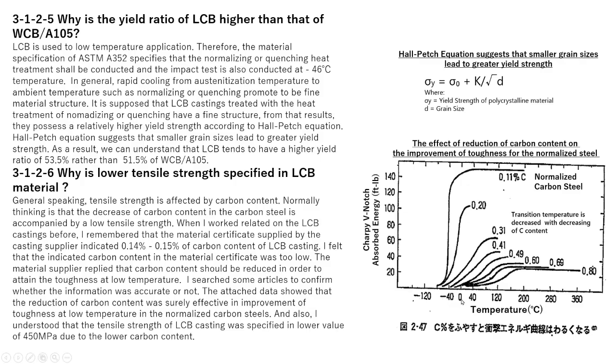Here is 0 degrees Celsius, the freezing temperature, and minus 40 and minus 50 are in these areas. The vertical axis indicates Charpy V-notch absorbed energy in foot-pounds.